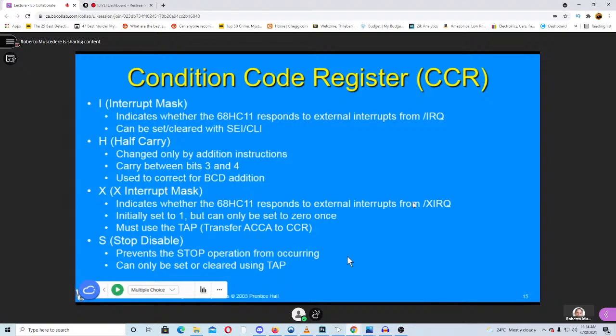I can say that earlier devices prior to the HC11 had a lot of issues with this kind of stuff. As I mentioned, the NMI thing is a problem that they had. You could achieve CPU deadlock easily. It's very easy to do on earlier CPUs. They didn't have a method for detecting undefined opcodes. They would just try to run them, and if it got to one, it would crash the CPU, and that was it. You had to turn it off. These ones have far better mechanisms for this.